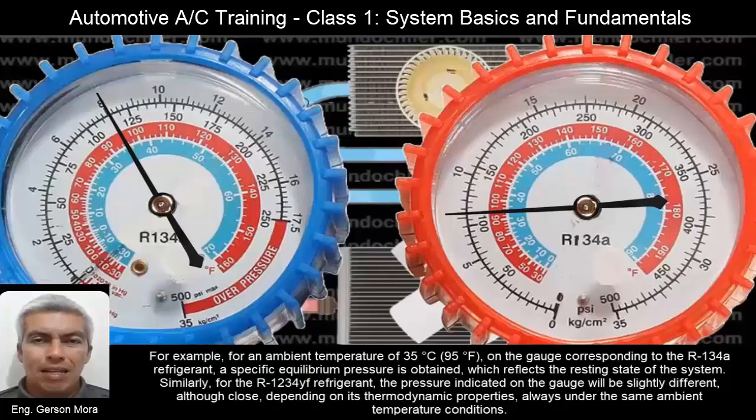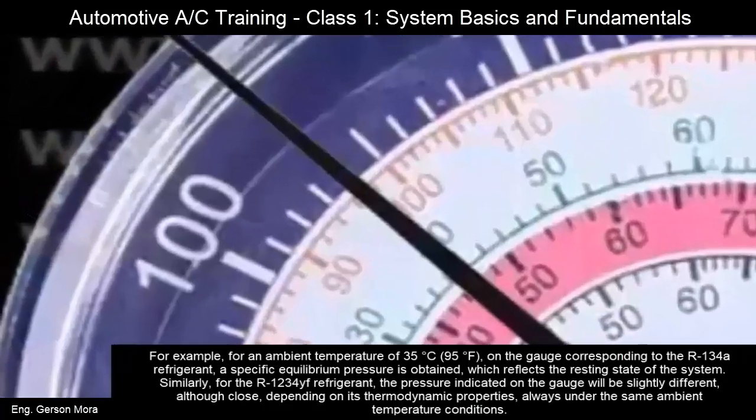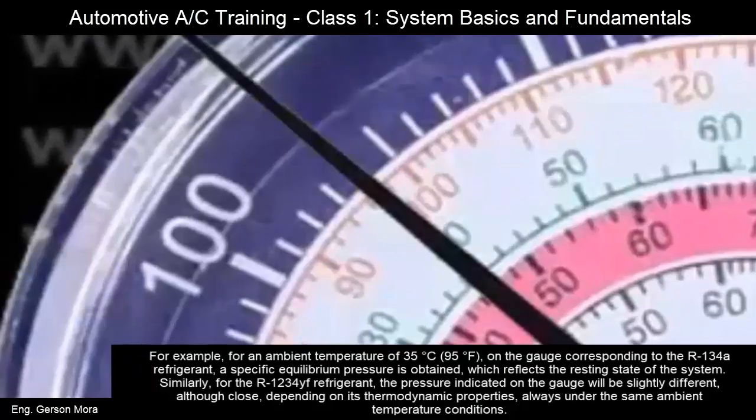For example, for an ambient temperature of 35 degrees Celsius or 95 degrees Fahrenheit, on the gauge corresponding to the R134a refrigerant, a specific equilibrium pressure is obtained, which reflects the resting state of the system. Similarly, for the R1234yf refrigerant, the pressure indicated on the gauge will be slightly different, although close, depending on its thermodynamic properties, always under the same ambient temperature conditions.